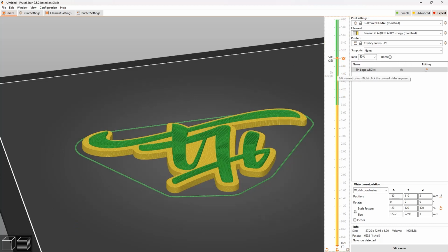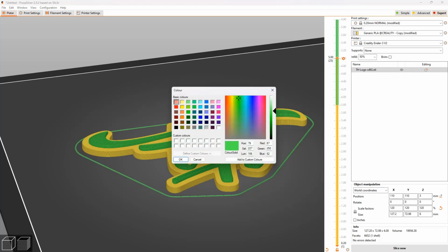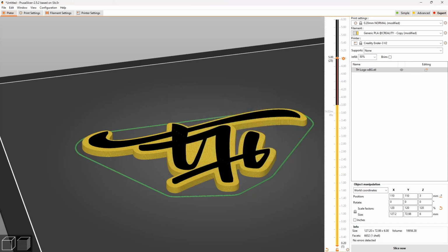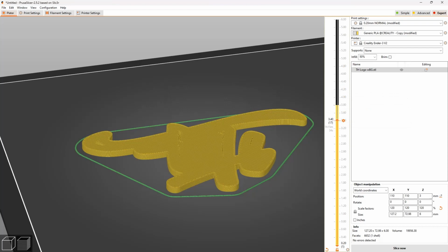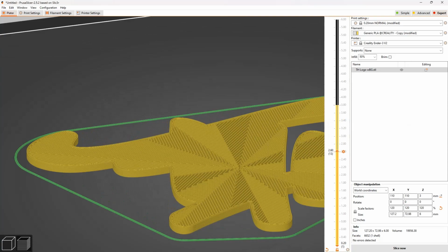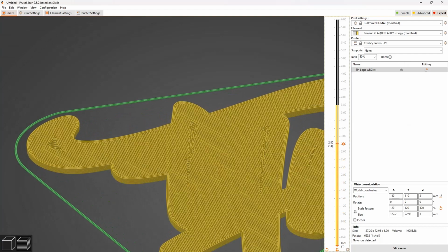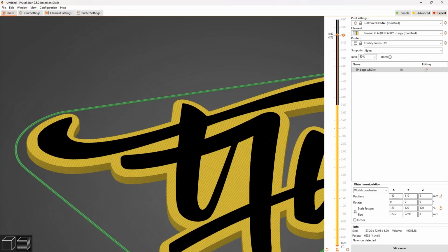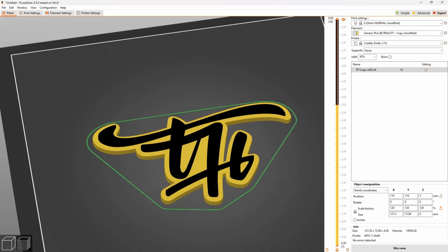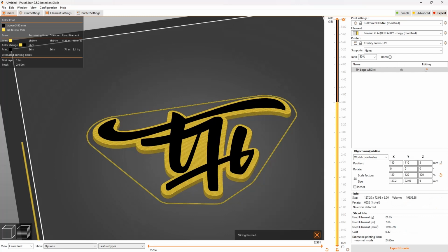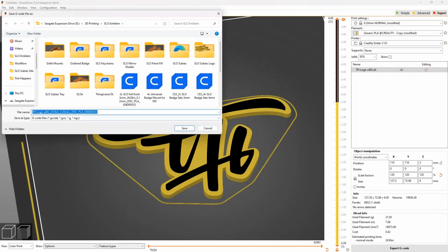And then Prusa here, you can change how it looks on here. It's not going to change anything at the printer. It's just for display here. So you can see there, that's how it's going to end up coming out. Your background color, and then it's going to stop at that 1 layer and wait for you to change it. This is what the octagram spiral looks like on the inside. So it's a little faster. It does a little spiral thing instead of going back and forth and all that. So it'll print up to that 1 layer, back it out, wait for you to change the color, and then it'll just wait for you to tell the printer to continue, and then it'll finish up.